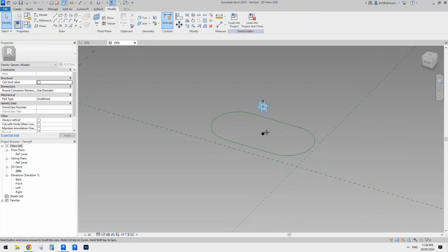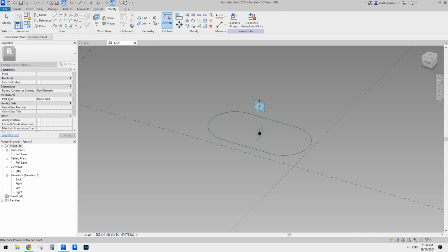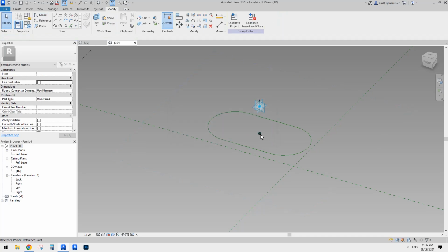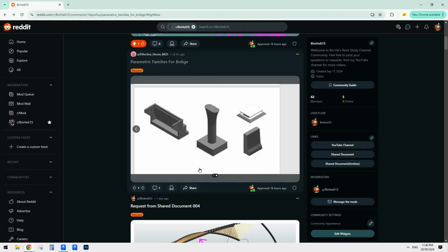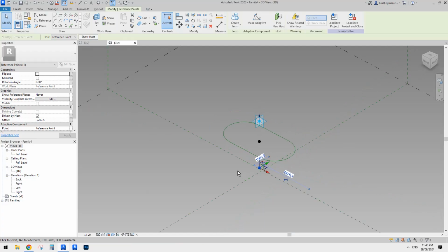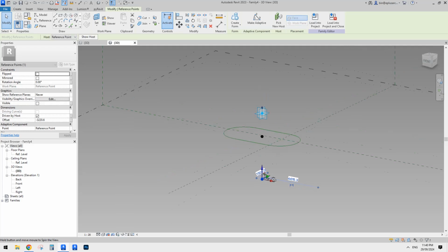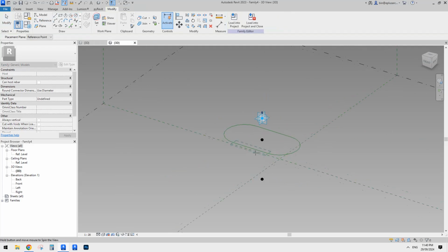Then we're going to place another point, draw on work plane. This time I'm going to place onto the horizontal work plane of this point, then place onto the point, click OK, and select the point, drag this down. So now we have another point for the profile, which should be a circle, right? Let's move it down roughly here, then use reference, circle, draw on work plane, set work plane, tab,